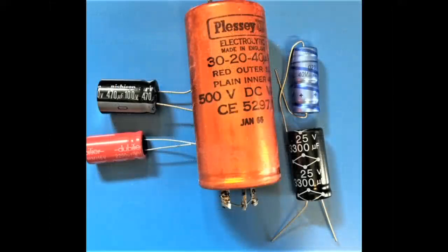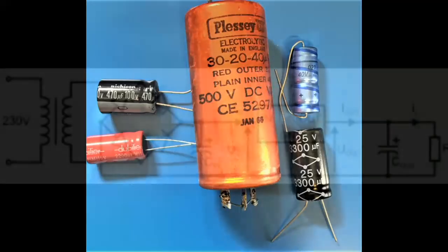The voltage rating on the capacitor is normally the highest or maximum voltage that can be placed across it, and it is called its working voltage. Generally, a higher voltage rating capacitor is placed in the circuit to allow for any voltage increases due to aging of other circuit components or surges such as spikes.